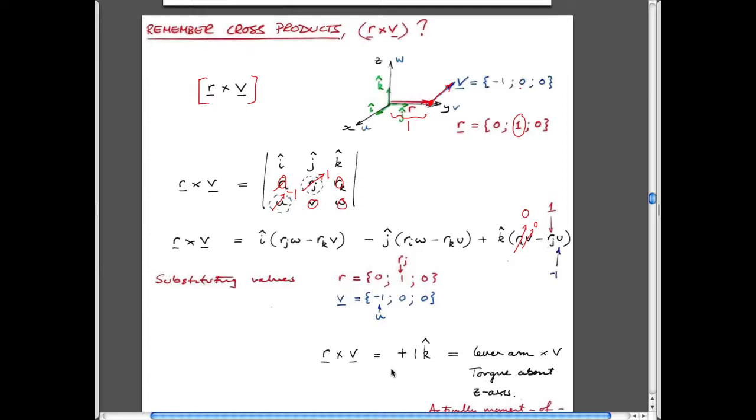And the sign convention is that we've used x, y, and z, but the sign convention for these rotational velocities is the right-hand convention, which is rotation in the direction of your fingers, and this is the axis. And so in this particular case, we have the vertical axis, which is z, which is my thumb, and the rotation that we have due to this velocity is in the direction of my fingers. If you look down on this, it's counterclockwise. I suppose if you look along the axis, it's clockwise. And so this is the positive rotation, and therefore this magnitude here is plus 1.